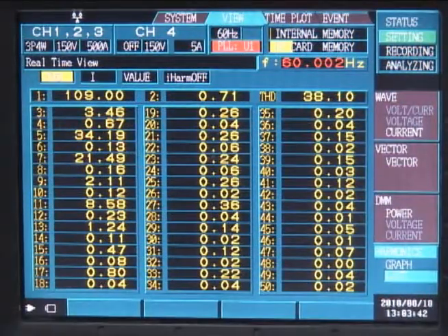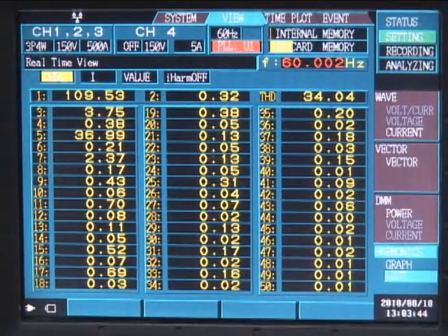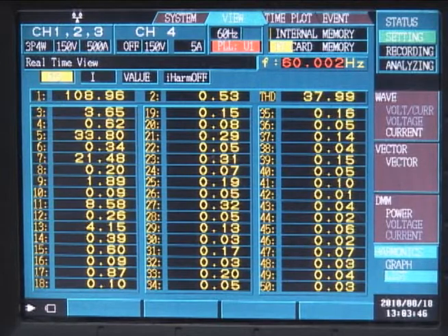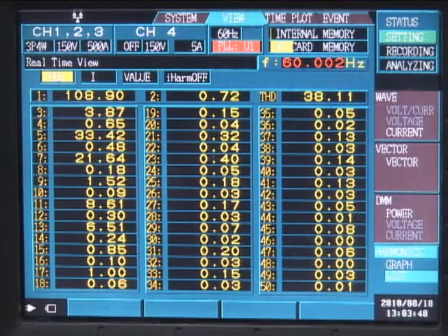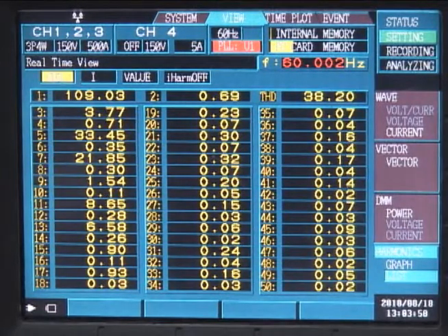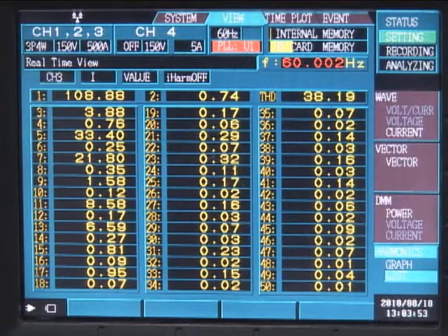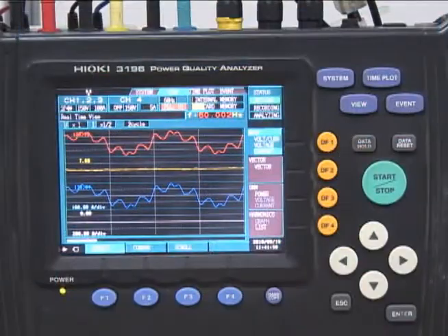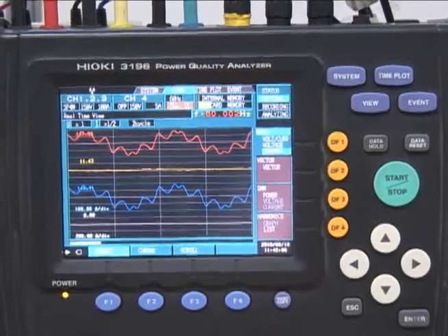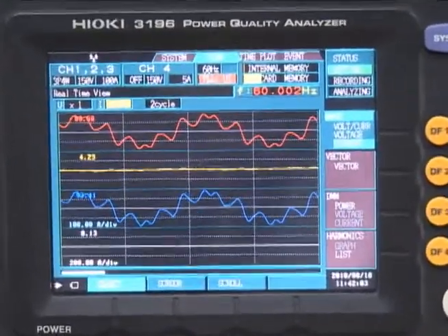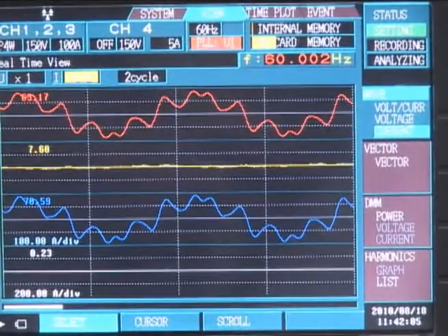The IPF active filter will now be connected in parallel with the load, and we will observe the load current, the line current, and the filter current for different programming of the filter. We will also analyze the line current spectrum. First of all, the load is switched on without the filter. The load and the line current are the same since the filter is not yet switched on.